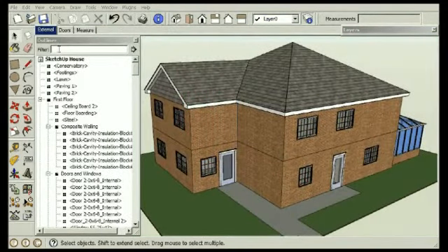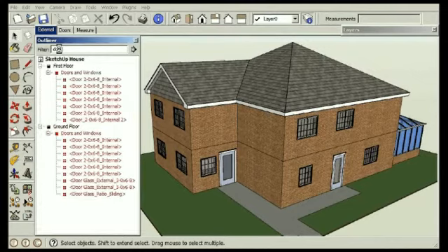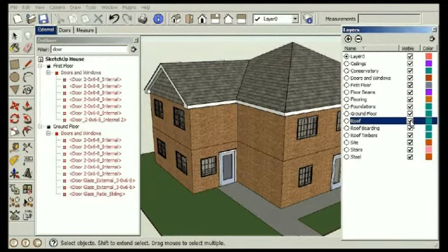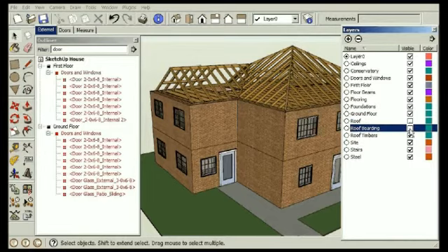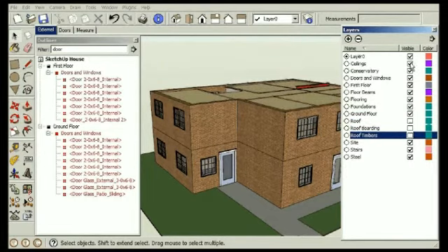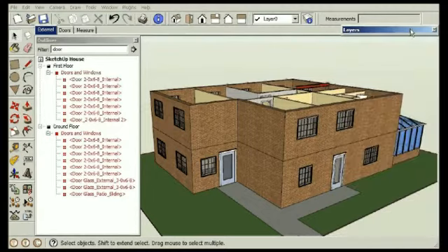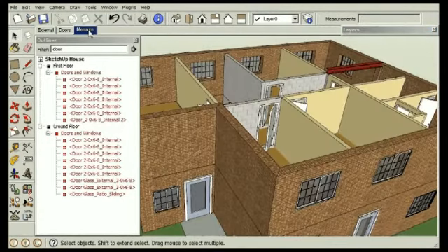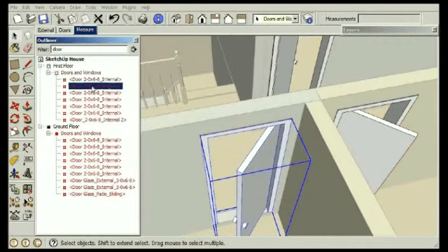In this model of a house, SketchUp can easily list just the door components. From the list, there appears to be 12 instances of a 2-foot wide internal door, which would be listed as such in an extracted bill of materials. The roof and ceiling layers are switched off to reveal some of these internal doors. When a door is measured, it is found to be over 4 inches wider than described. The original geometry has been scaled to fit.